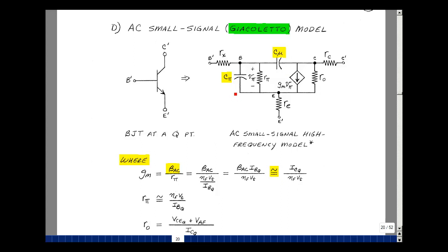But when he did that, he found that this term didn't vary with frequency. This is very nice in that this is an equivalent circuit where all the terms in here are constants. Now again, this is an impedance. It has a term multiplying that varies with frequency, but this takes us back to basic circuit design. And a lot of model development is just that, using common sense to figure things out. This formula for the gain bandwidth product is derived in the supplemental problem sets. I'll have you look at that and see some of the details of how the AC beta varies with frequency.